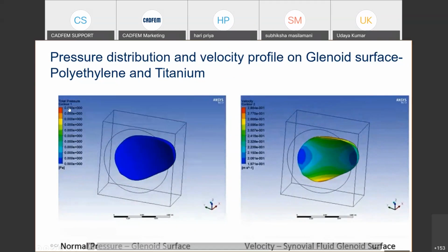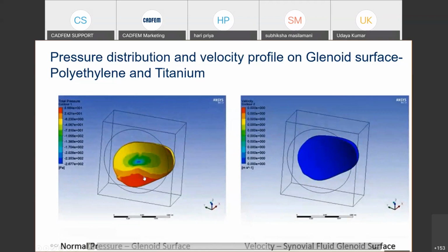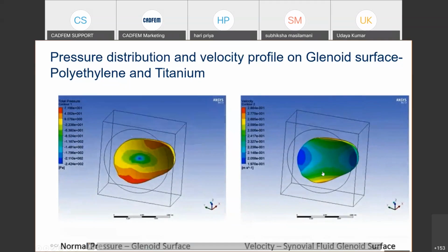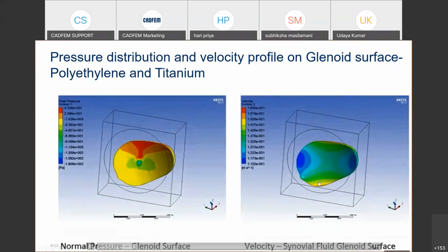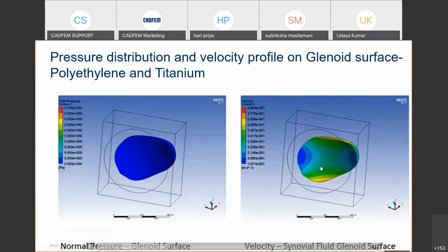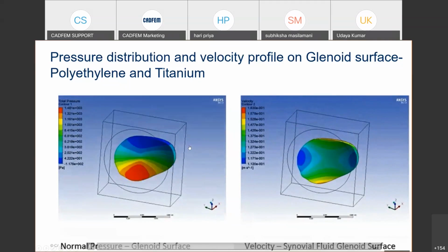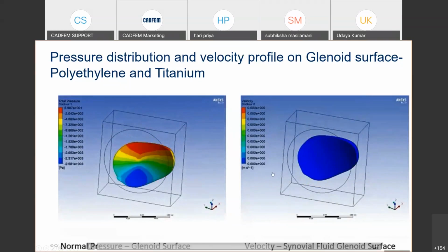You can see the same boundary conditions, but at the same time the pressure variation is a little different here. This is due to the deformation, or the pressure causing some small oscillations inside the solid bodies. That is why you can see small changes in the velocity profile too. As polyethylene is comparatively flexible, small oscillations of these solid parts are also happening.